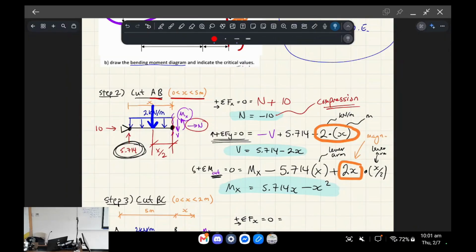because the question is basically just saying it's a hinge, you want to try to find the reactions. In my opinion, it's actually more confusing flipping around the free body diagrams too much. So I would keep the orientation the same to solve the support reactions. However,